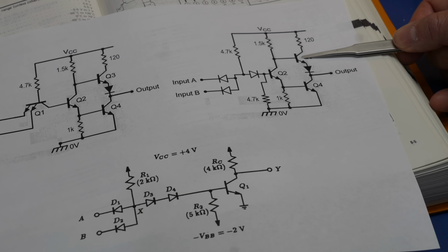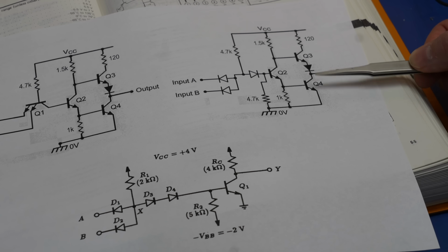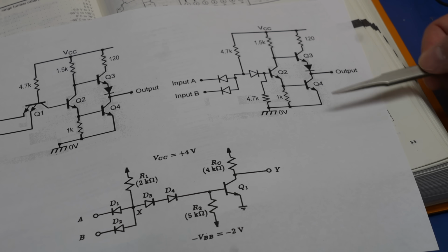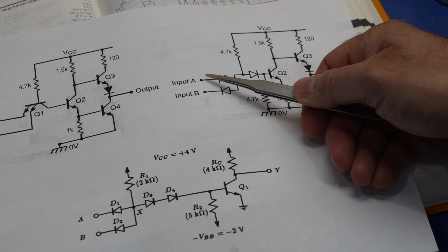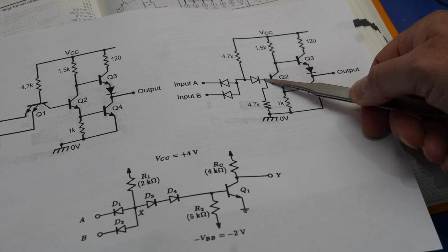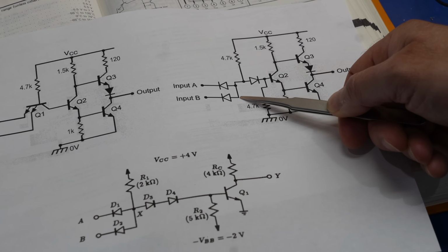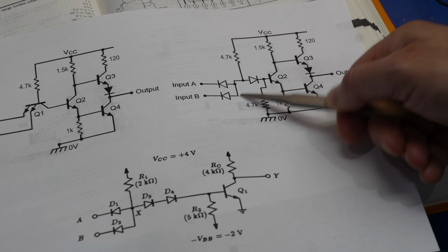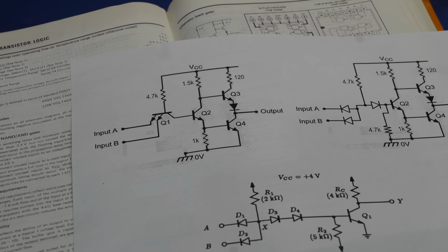One transistor to pull the logic high, and another transistor to pull the logic low, so that the current can go either way fairly strongly. So it gives you a lot of fan out. You see that's an NP junction, and that's a PN junction. Huh, that looks like a transistor. And here's another NP junction. Oh, that looks like a transistor with two emitters. And that's of course exactly what they have done in the final TTL gate.